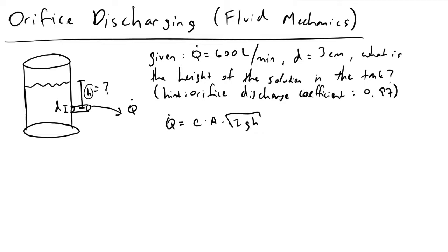Another important thing to note about this orifice coefficient C is that these numbers are typically about 1. It's never going to be greater than 1, but it's also not generally going to be about 0. So you're looking at values between 0 and 1. The closer it is to 0 indicates that you have more frictional losses present. So if we were using pipes that had lots of surface area causing the fluid molecules to shear against the walls, generating lots of friction, we would expect to have a lower C value because intuitively we would expect to have a lower flow rate given more resistance through our orifice.